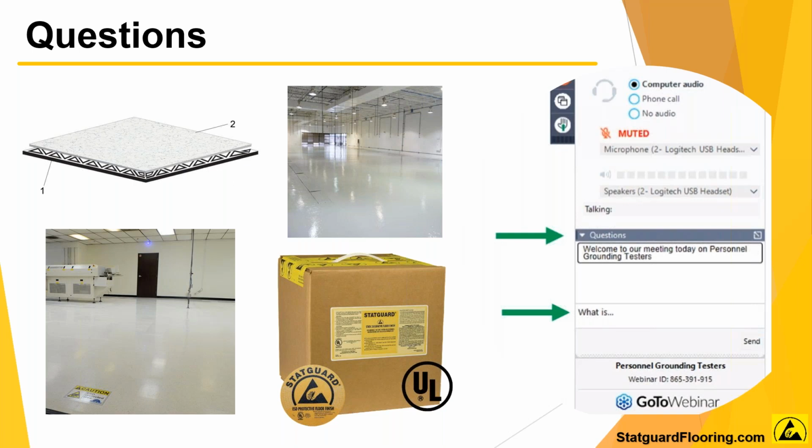Our standard floor finish is 18% solids. That's a 3-coat requirement. Our low VOC floor finish is 23% solids, so that's a 2-coat requirement. Depending on the floor finish, it equates to either 3 coats or 2 coats. There's a 1-hour waiting period between coats. You let it dry and the floor is being used the next day. Okay, thank you. You're welcome.